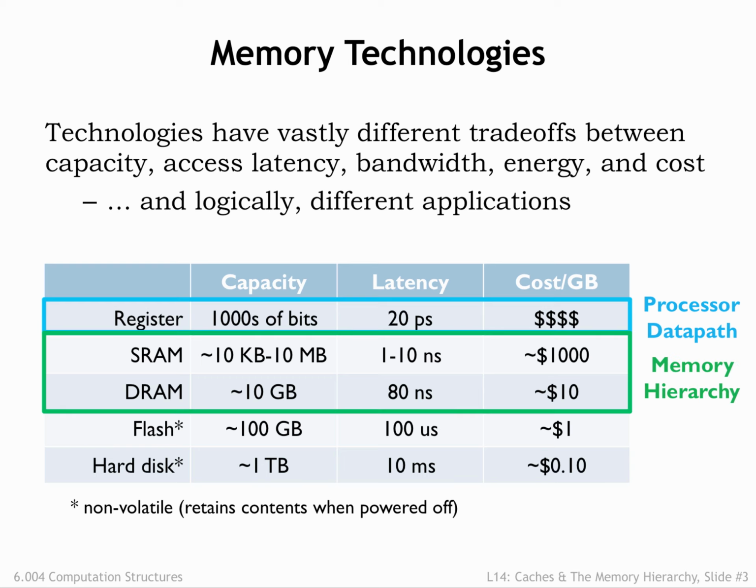Static and dynamic memories, which we'll discuss further in the coming slides, offer large capacities at the cost of longer access latencies. Static random access memories, SRAMs, are designed to provide low latencies, a few nanoseconds at most, to many thousands of locations. Already we see that more locations means longer access latencies. This is a fundamental size versus performance trade-off of our current memory architectures. The trade-off comes about because increasing the number of bits will increase the area needed for the memory circuitry, which will in turn lead to longer signal lines and slower circuit performance due to increased capacitive loads.